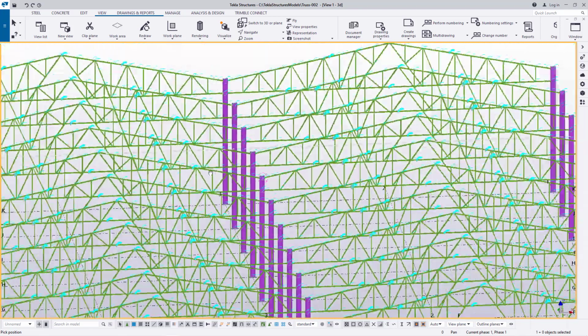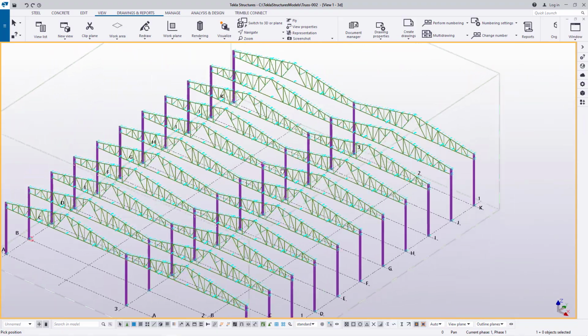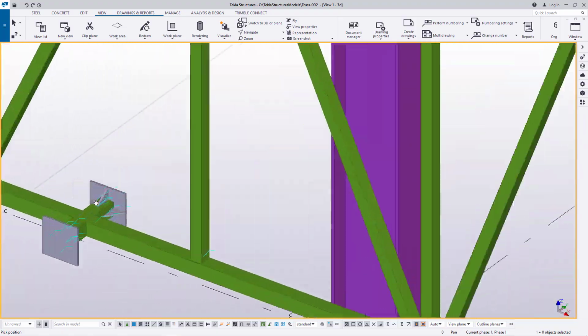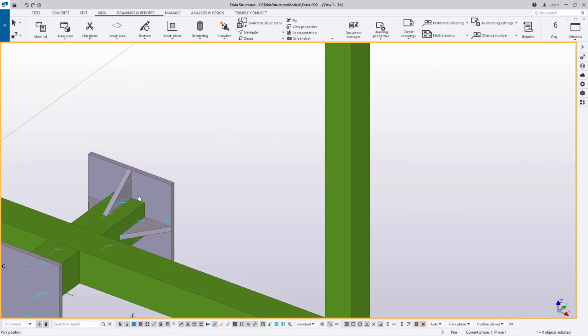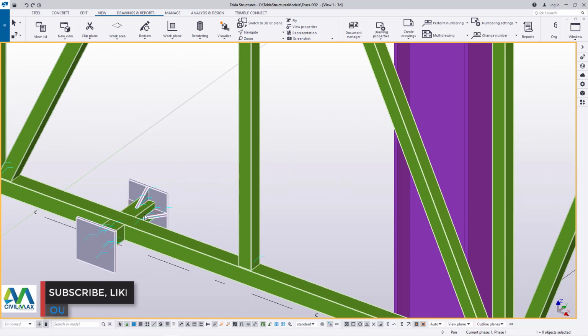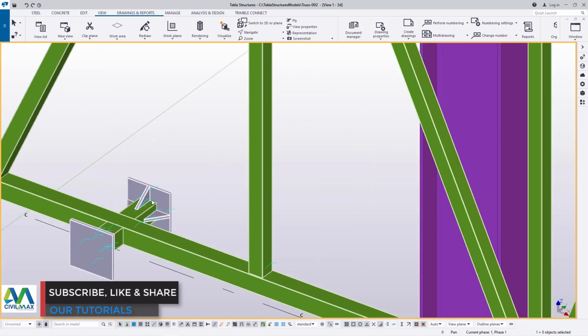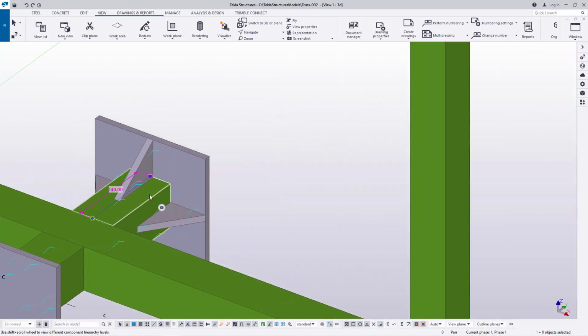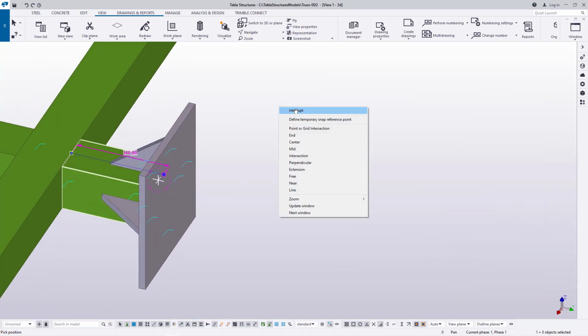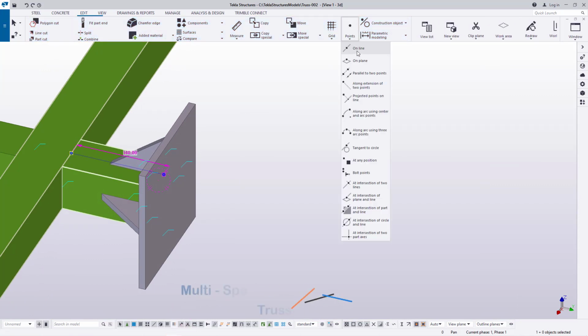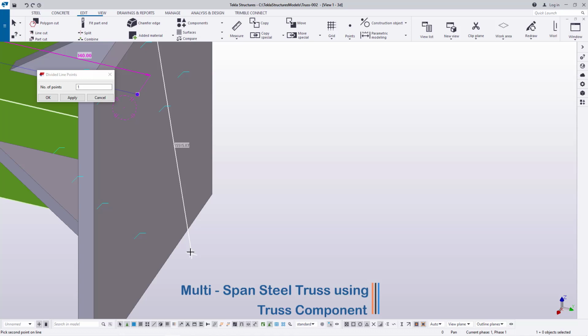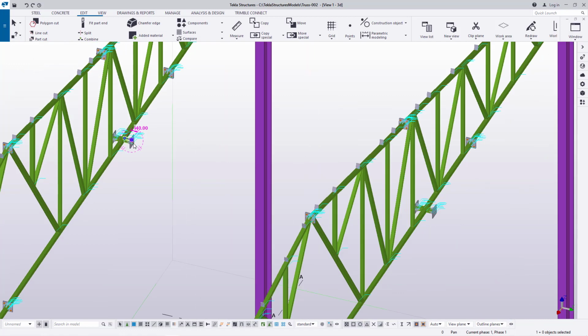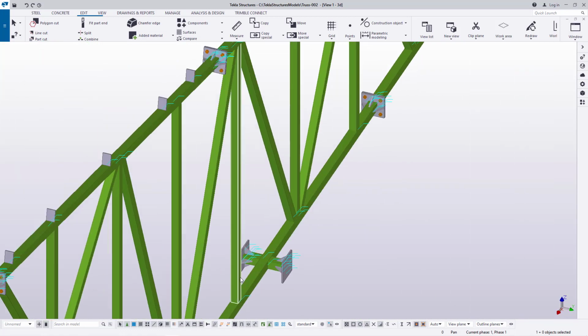So whatever is remaining is just the purlins, the bracings, or the tie beams. So the tie beams can be placed accurately. What we are going to do, just disable the assembly first, and first of all try and check the centers of these members. I'll come to Edit here, pick Online, and I'll define the midpoint here, and I'll get the midpoint right there. I'll click OK.